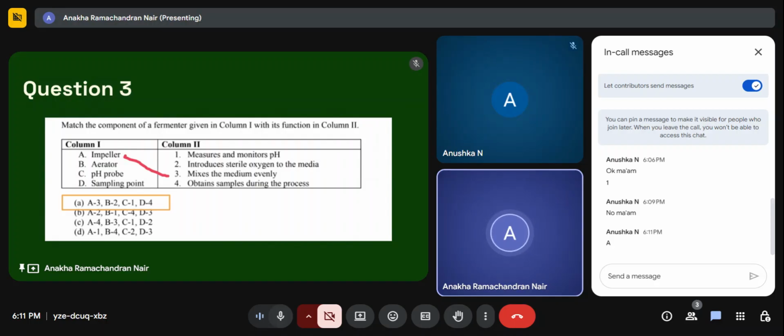And they might settle at the bottom. And when that happens, imagine this is the bioreactor, and the soluble compounds are settled because you have to keep it for a long time, right? But the cells are here also, and they don't get the nutrients, so you have to keep mixing it so that there's a uniform condition, and that also helps spread the gases inside, right?